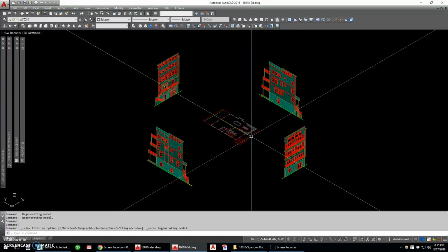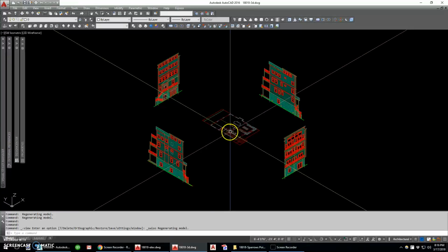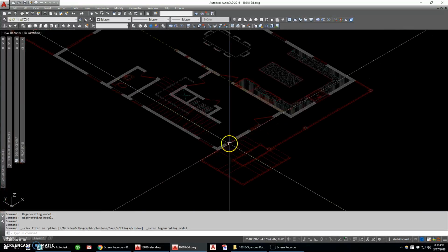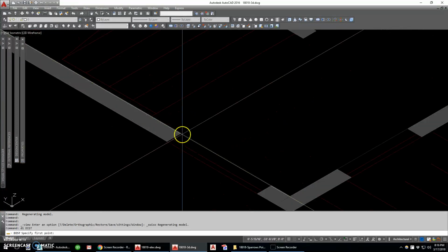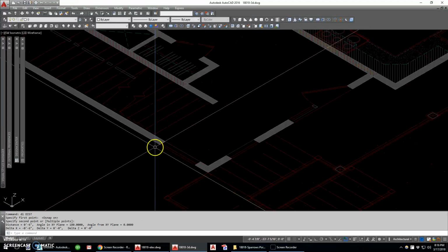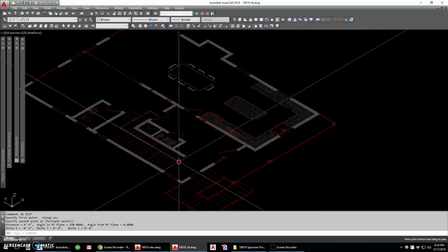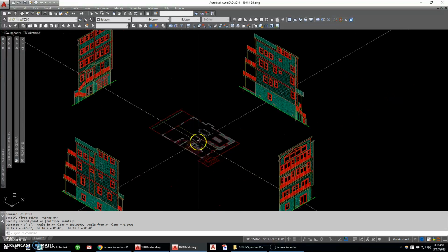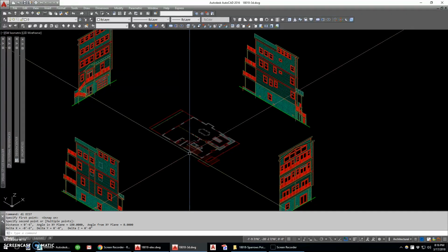Okay, the next step here is to create the walls of the house. This creates the walls and the roof. This gives us a building envelope to work with. We want to use the simple walls. In the case of most residential architectural, you're going to have wood framed walls. The architect has these walls drawn as 6 inches thick, which is probably a 2x6, but the drywall is not reflected in the lines. I use whatever the architect did. Usually they're 4 inches, 4.5, 6, 6.5, something like that.